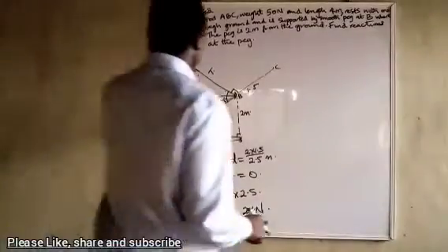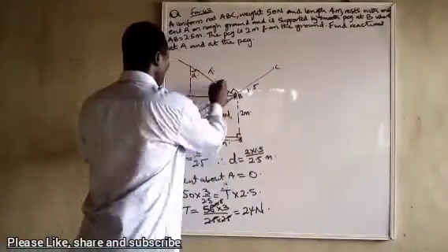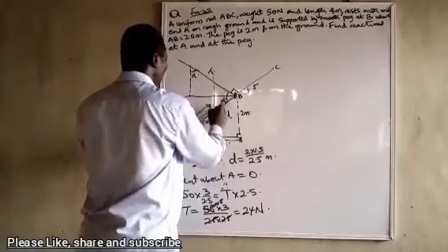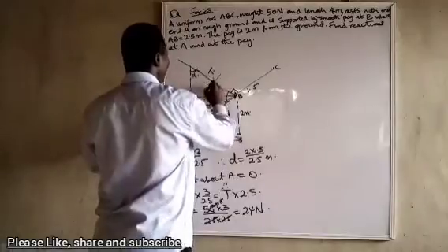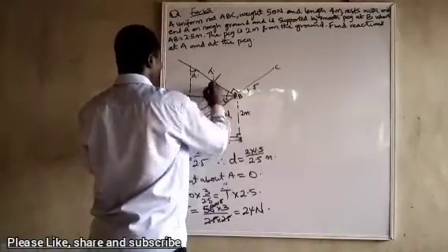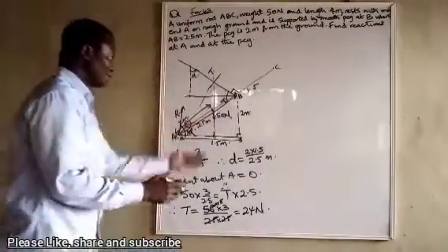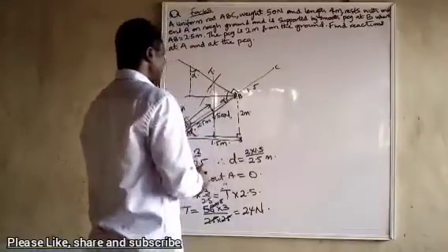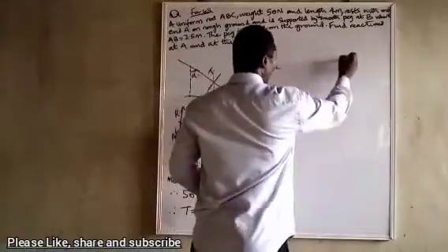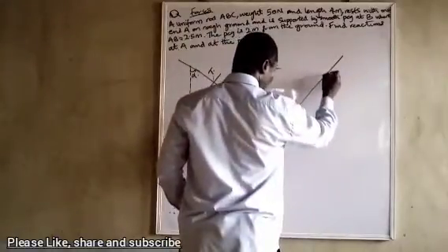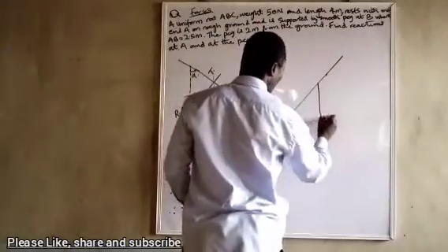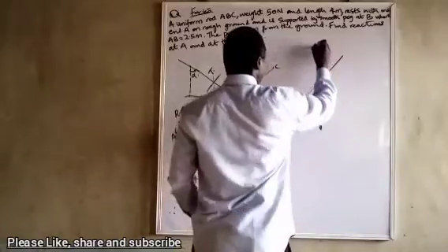For this, you can draw the diagram. You see, this 50 will meet this one here, and this one will meet at this point. All of them must pass through this point. So with this, you can draw your triangle and get, by the ratio, the forces. Let's see what it will look like. We have something like this. 50 comes here and goes like this.